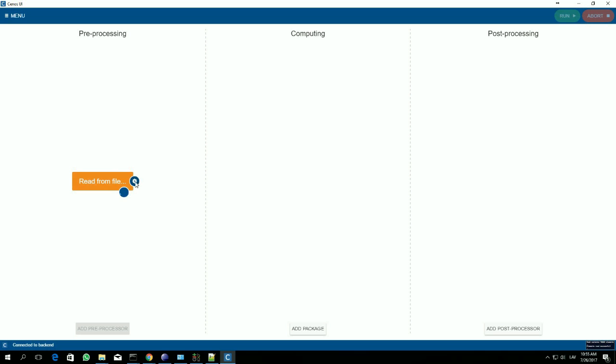Now you have here an option to change base units, and actually if you have created CENOS block and created geometry, you can just continue in the same workflow, but you also have to select the mesh base units. By default it's meters, but I have input everything in millimeters, so I'll choose that one. It is important that you are consistent, so you always input everything in millimeters.